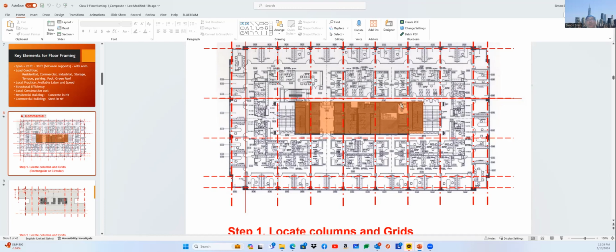Those are all essential elements located in the middle backbone zone, let's say the core, right? And we engineers typically use either steel frame or concrete frame, which is a concrete shear wall or steel brace frame. For a 30, 40-story building, maybe 20, 30 years ago in New York City, they used a steel frame for the lateral system, but that is extremely expensive now.